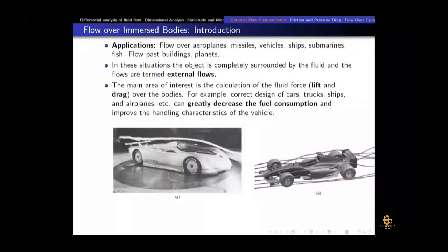And what is the motivation to study the external flows? In this we want to calculate how much drag force is being applied by the fluid on the object, right? Because that object, like if it is a vehicle or aeroplane, has to overcome that drag force to move forward. So if the drag is less, then the fuel consumption would be low. And if the drag is more, then the fuel consumption, that is the power required to oppose that drag force, would be high.